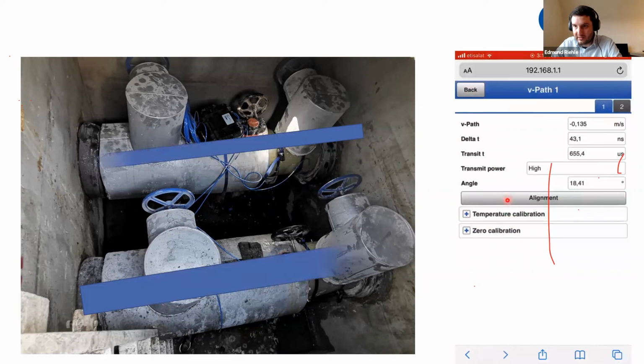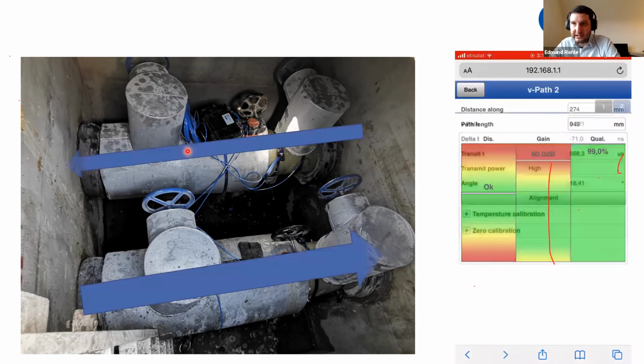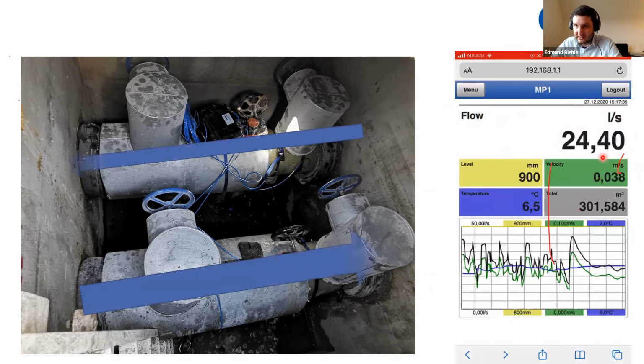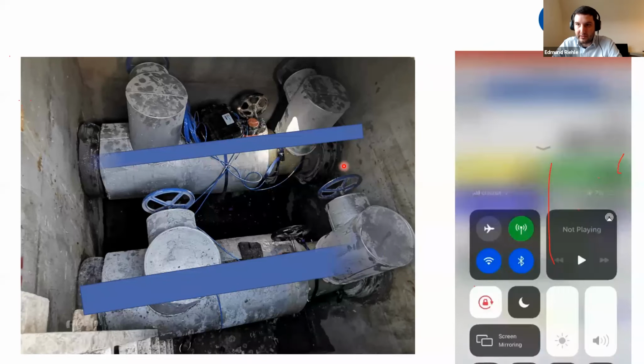So we have the negative flow velocity here and the positive flow velocity there, and the flow velocity of the supply is bigger than on the return, and therefore we have this deviation. We can see the differential flow directly, and this is the leak rate which is really happening in between the supply and the return pipe there.